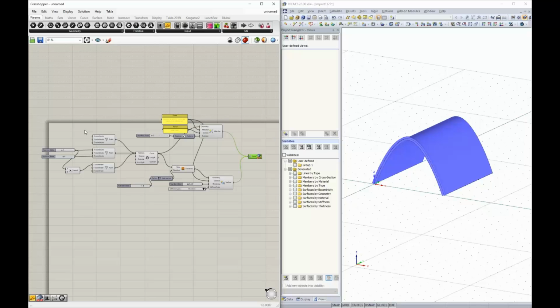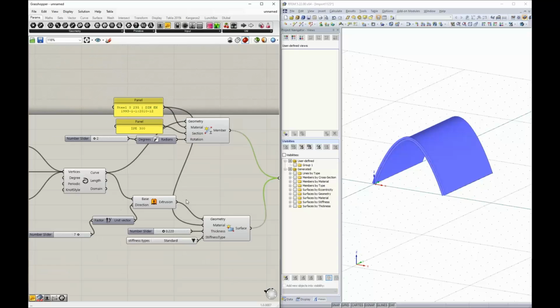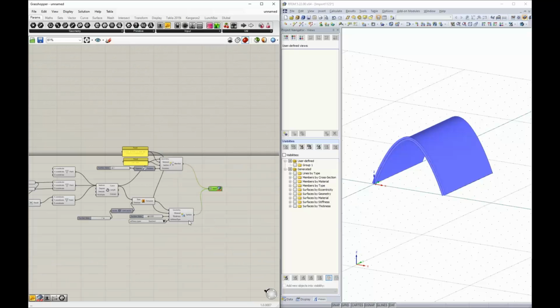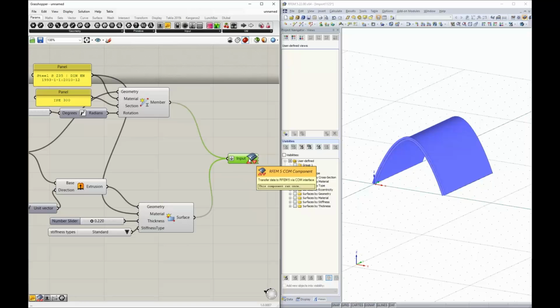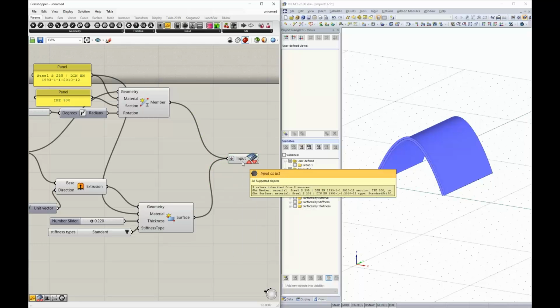Very basic example, I know. The goal was more or less to show you how you can control the input of the Dlubal specific parameters. Just a couple of additional pieces of information, maybe. If you use the export component here, please flatten the input. It relates to the fact that we always expect simple lists. In case you know Grasshopper much better, in some cases you have tree-like information structures, then you have to flatten them before you export them.